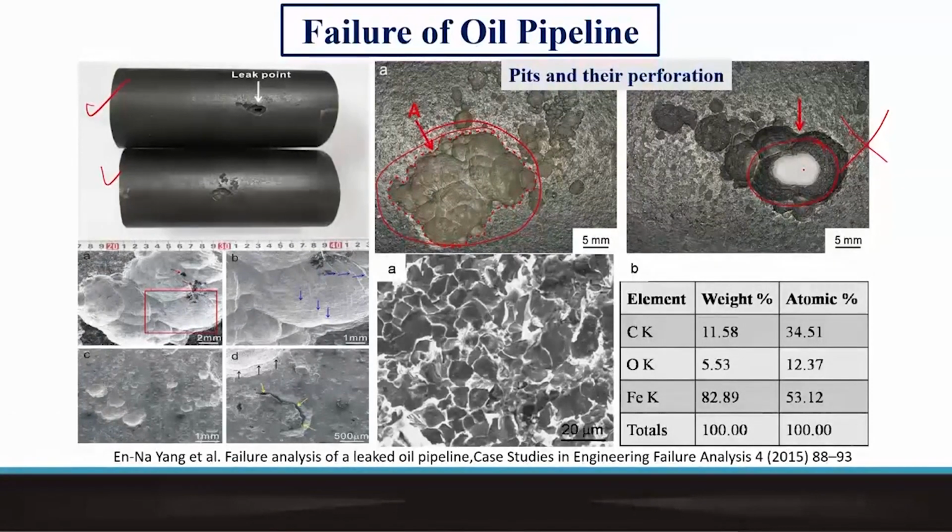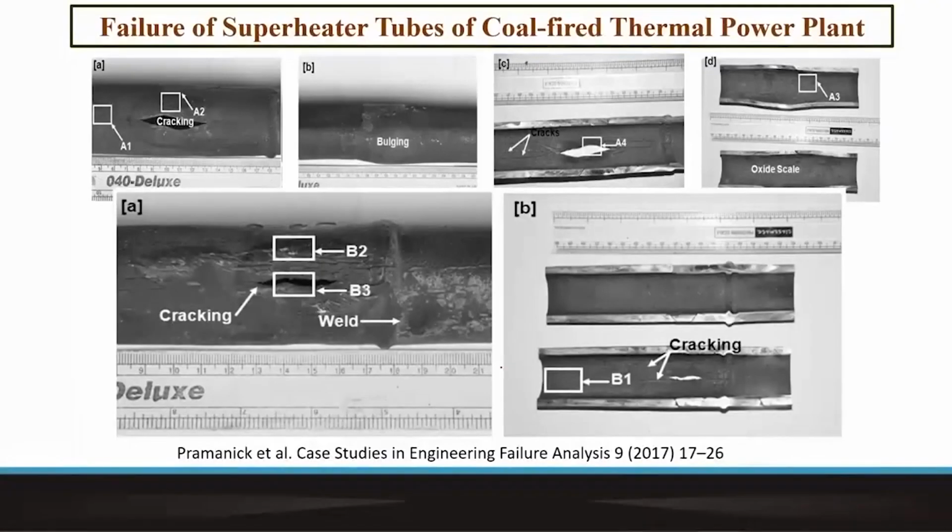And if one goes through the failure analysis of these failed parts, then one comes out with various forms of degradation, including formation of corrosion products, rendering the entire steel pipeline, or the surface of the pipe, entirely brittle and converted to oxides or some other compounds.